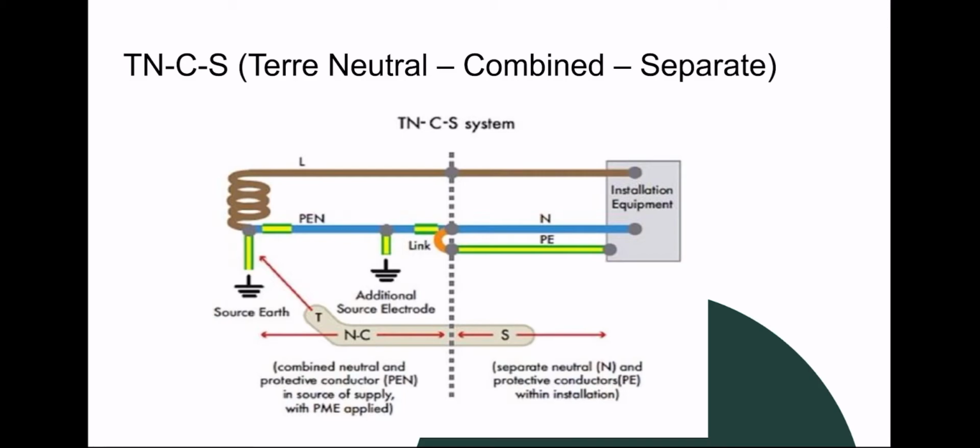With this system, a neutral conductor can function to return the earth fault current that might arise on the consumer side back to the power source. In this system, the equipment in the consumer installation only connects to the ground terminal provided by the power source.